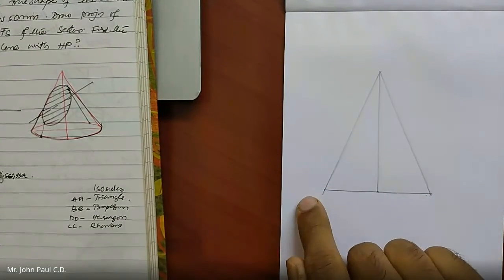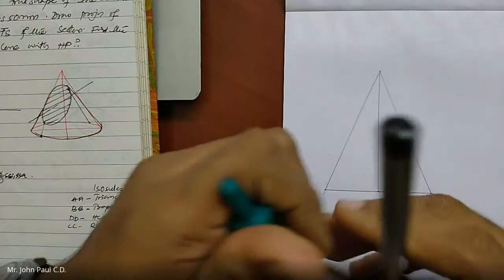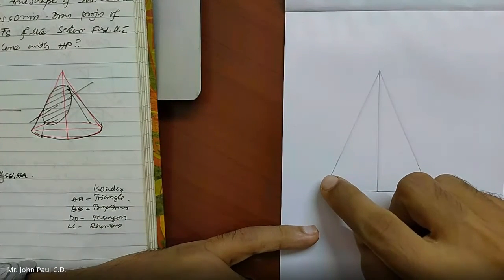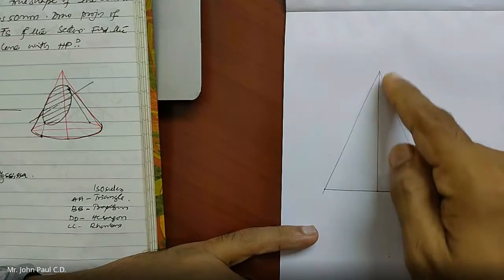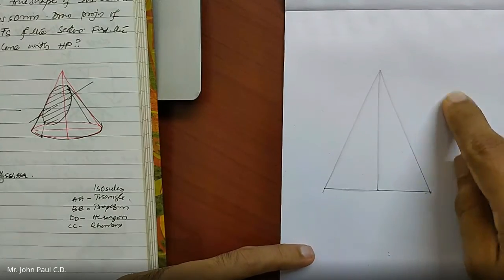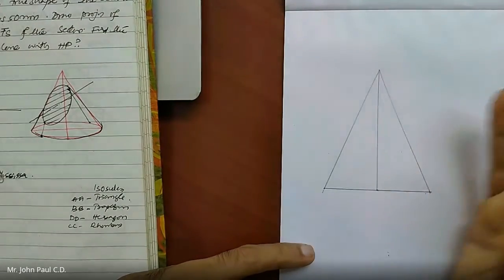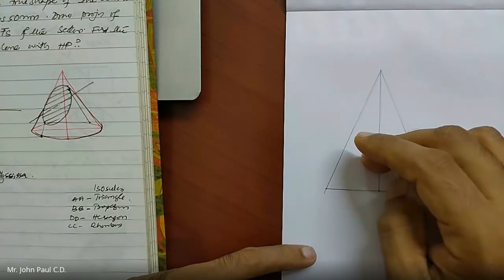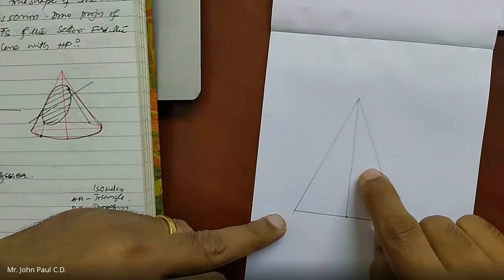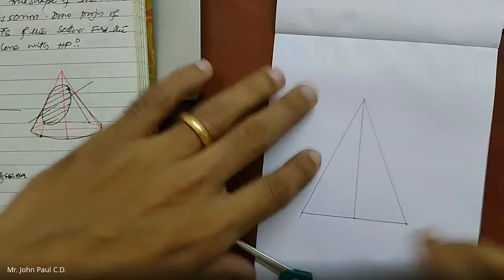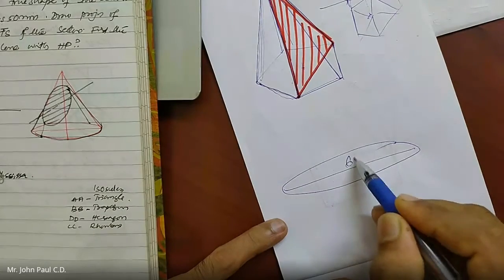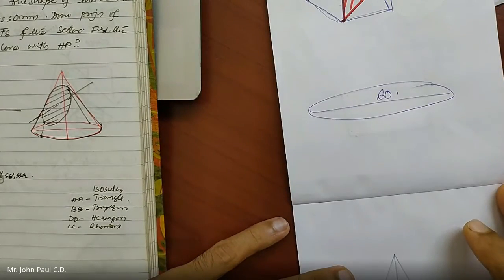So it says that it has a base circle 60, height 70. I have drawn here, and it says that it makes a cone with the true shape is an ellipse. To get an ellipse, what do we need? The plane should be inclined to the base and cut it, right? And it should not cross the base. That is, it should not cut the base, it should cut only the lateral surface. So it goes from here, and I should get an ellipse here, and the major axis of the ellipse has a dimension 60. That's what is stated in the question.